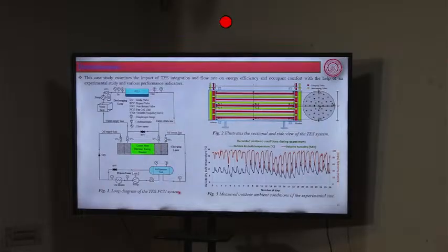That way, the overall round trip efficiency of the thermal battery gets enhanced when you stack the phase change materials in a way of reducing melting point. So as I was saying, nitrate and nitrite were cascaded to get this advantage of utilizing the melting point of one to get to the next phase of melting.